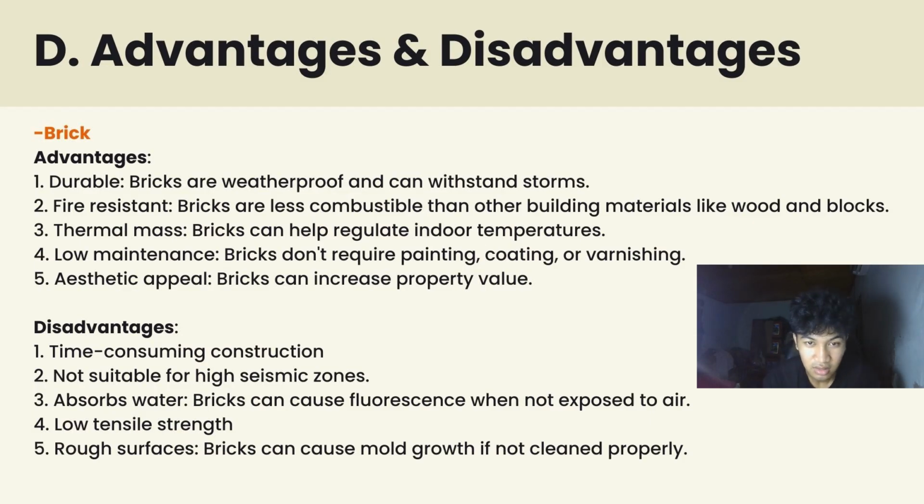For brick, the advantage is first, durable. Bricks are waterproof and can withstand storms. Second is fire resistant. Bricks are less combustible than other building materials like wood and blocks. And third is thermal mass.